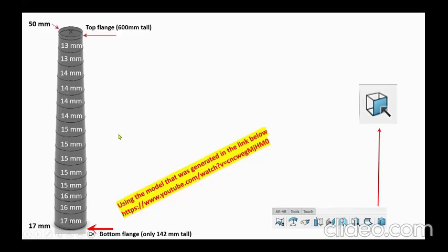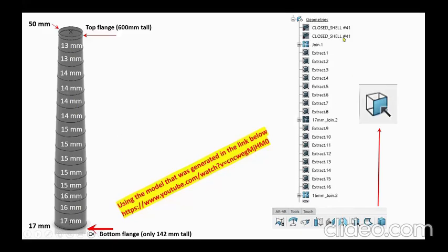and then assign section properties and mesh them one by one. That's why I have a lot of extracts. For example, I extract the bottom 8 patches, there's 4 here and 4 below it, and join them. That will give me my first join, 17 millimeter, and I can assign thickness to it later on with shell element, and I can mesh it. And then I extracted the next 8 layers, 16 millimeter, and joined them.